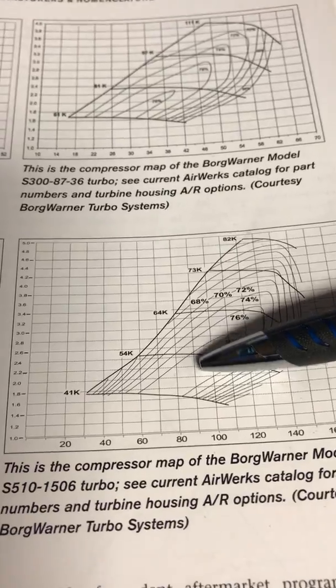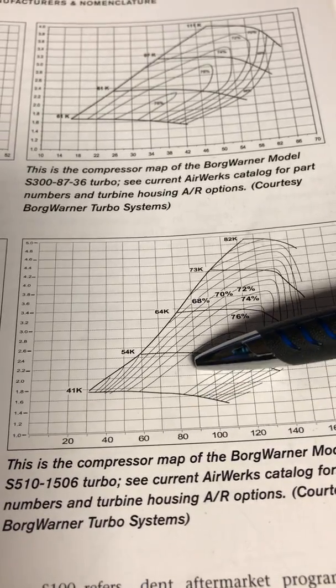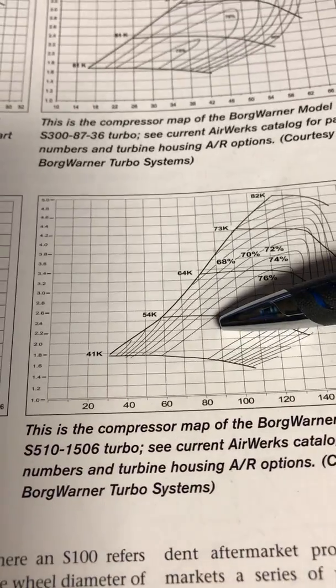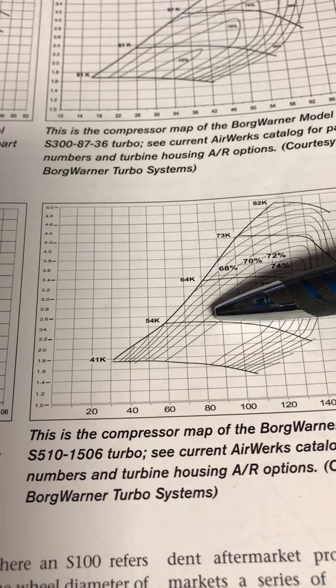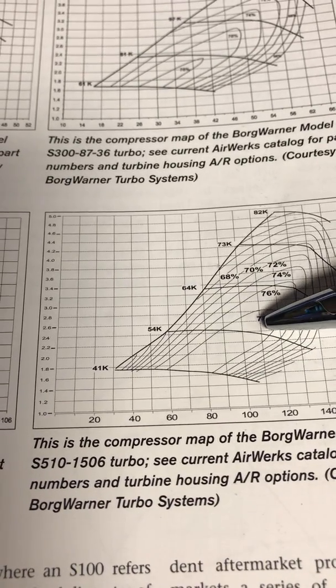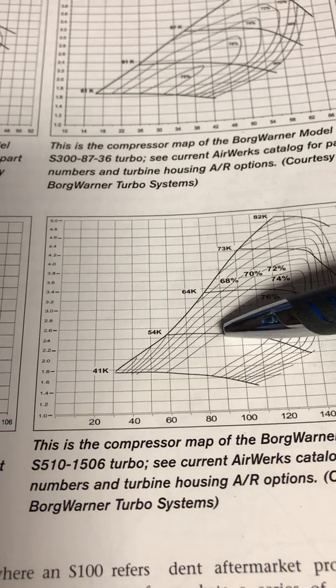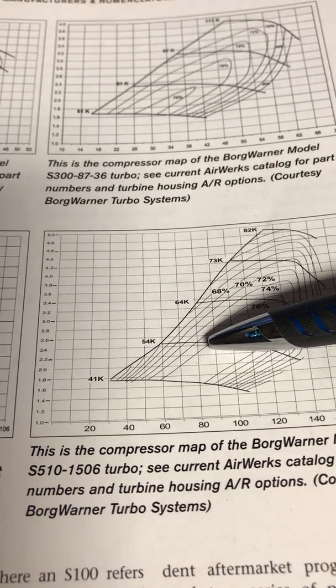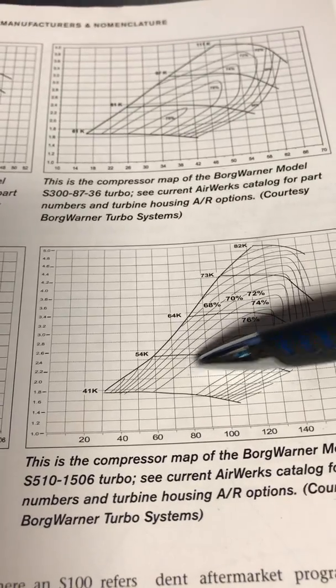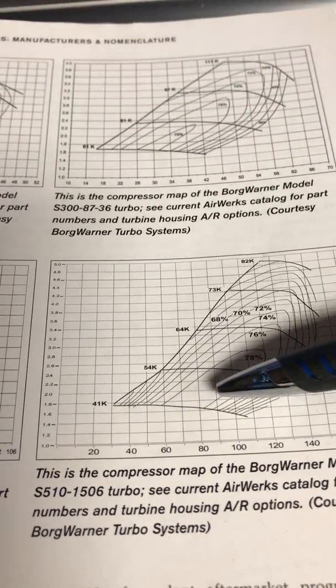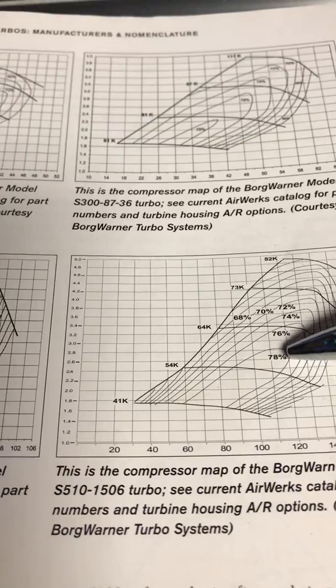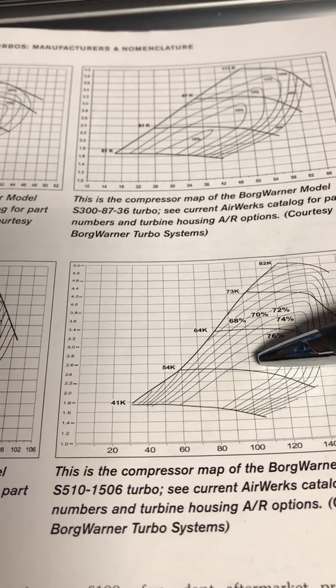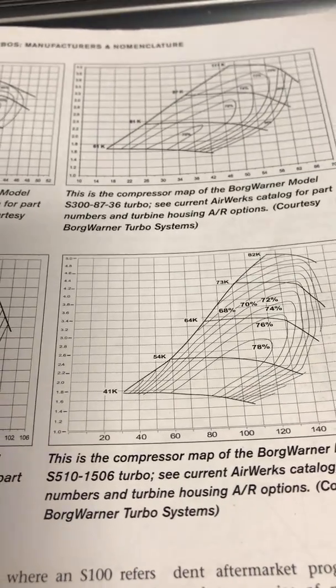What compounding does is allow you to take this S500, put out 85 pounds a minute. Guess what? It's in the 78% island because you're only running at a 2.2 to 1 pressure ratio. You're talking 25 pounds roughly. That's why compounding is so good, because it allows you to run this thing at 78% instead of trying to jack it way up here to where it's making hot air, basically.